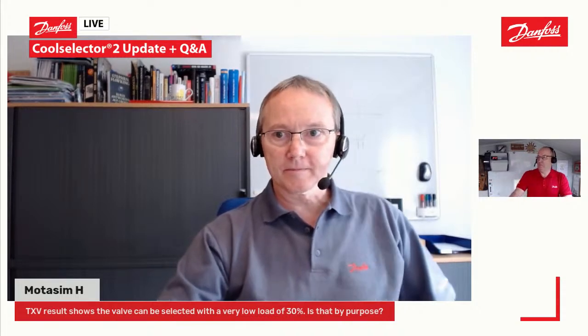Norbert, a question from me to you, actually, as we're talking about loading of an expansion valve. That's for a TXV. What about if we're talking about an EEV, an electronic expansion valve? What about the low load percentage of that one? The low load percentage usually is about 10%. Depending on the valve design, we have a variety of different types you can use as an electronic expansion device. It may vary, but it is around down to 10%.